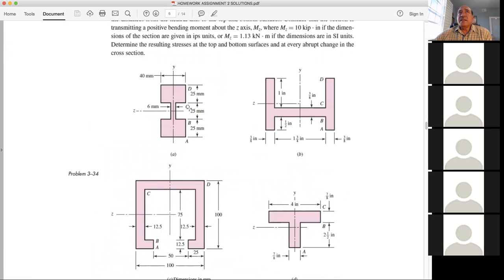There's a bunch of ideas. When you have an I-beam, you can take the I-beam simply as the difference between a rectangle on the outside, and you subtract the second moment of area of 2 rectangles that are carved out. So subtraction is okay. You can do it by one big rectangle and then subtract smaller ones.